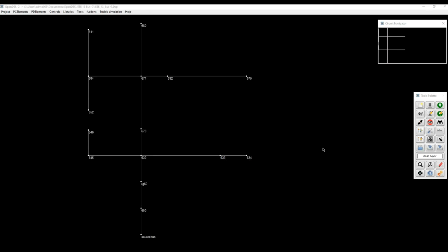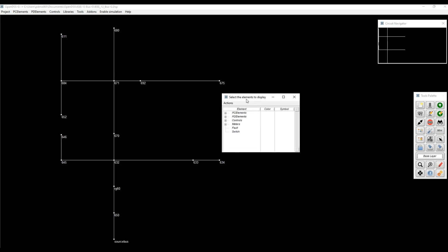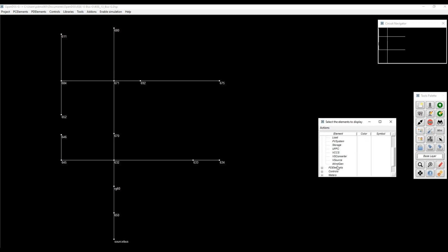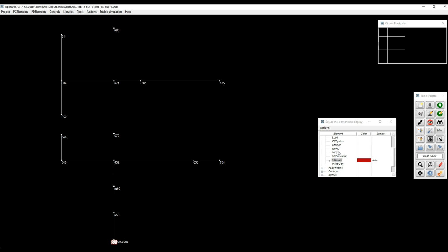Among the features that the new interface offers, we have one that is very special, and is the ability of copying or replicating an existing element. In OpenDSS, that was intended to be done with the property like. However, that one is not maintained anymore within OpenDSS, so we don't recommend to use it. So here, what we're going to do is we're going to create a new transformer. In this case, I'm highlighting just the V sources and the transformers that we have on one model that probably you know very well, which is the IEEE 13 bus node test.